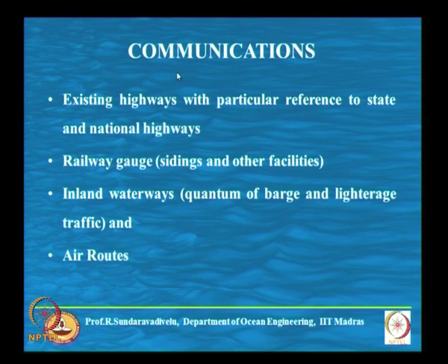The next, first it is the location, then the communication. Communication means what are all the existing highways, with particular reference to state and national highways. This is very important because even before construction, to carry out the survey, if somebody has to go to that location, he needs to know what the existing communication facilities are, railway gauge, sidings and other facilities. For railway lines, we provide a siding to many ports, so there is a separate line going that you have to give. Then inland waterways, quantum of barge and light craft traffic, and air routes.